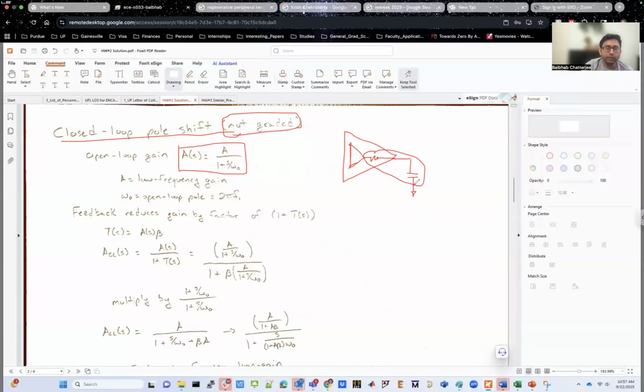And that's why, the basic way the low-pass filter's transfer function is written, you see that the transfer function of the open loop gain of the real op-amp with a finite bandwidth is written in the same way. Where A is your low frequency gain or zero frequency gain. Sometimes in books, you'll see it written as A naught. That just means it's A at zero frequency.